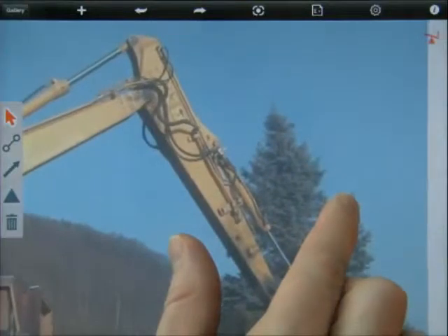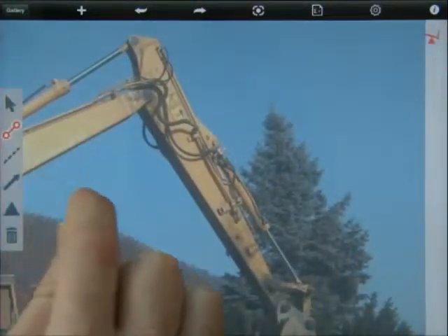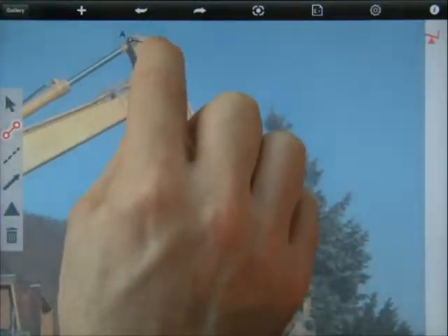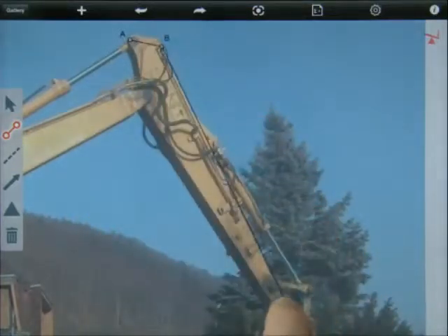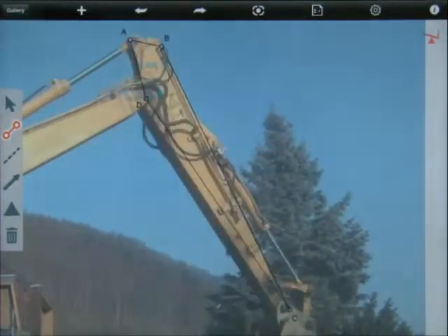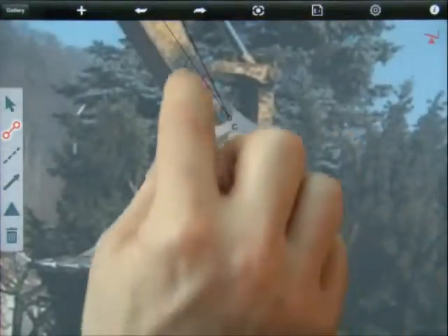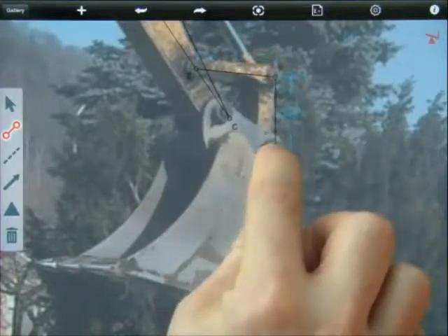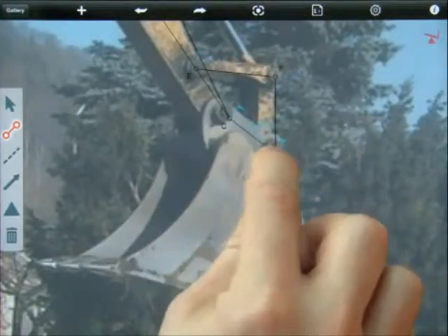Select Create Elements and draw your line segments. Tap, hold, and drag to create. Lines snap vertically and horizontally. You can snap to endpoints, midpoints, and you can even infer your endpoint and midpoint snaps. Dimensions are created automatically as you sketch.